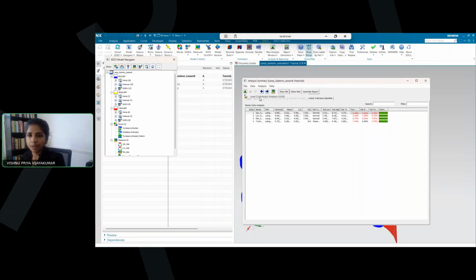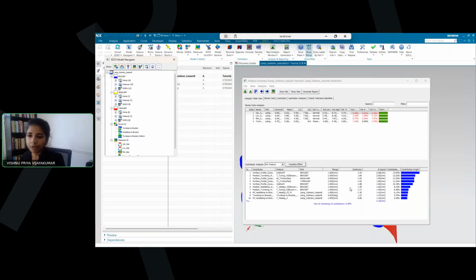Similarly, if I do the same thing for the HLM file, I pick the file from the server, and that gets populated on the screen. Now the user can go over the results and understand them. So in this way, you can send the HST-HLM file to Teamcenter, save it there, and retrieve it back and view it within the software. So that's about the results.